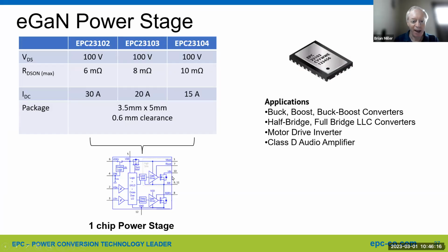One nice thing about GaN is you can have an optimized, say 100-volt, power FETs, but the little FETs that make up the gate driver, the little FETs for the level shifter and so forth, can be a lot lower. They could be 20 volts or 10 volts or something like that, just because they can be smaller. It's a lateral device. You can have those together. So it does work out very well.